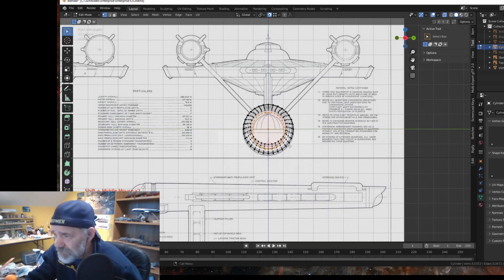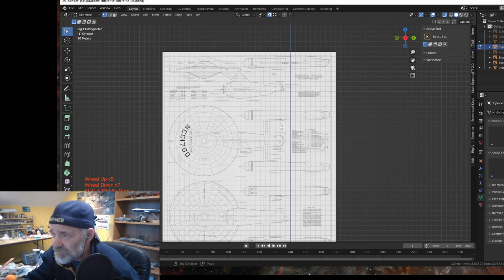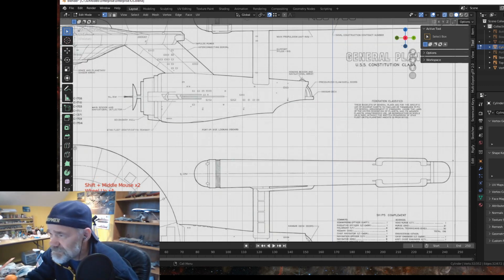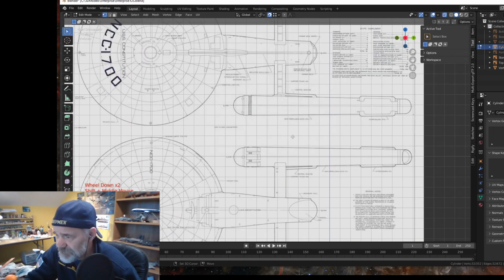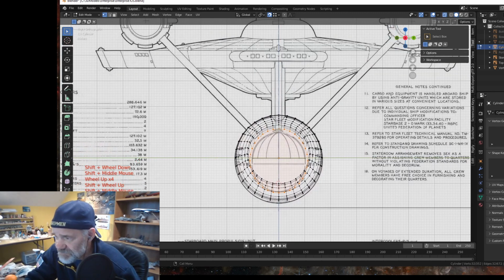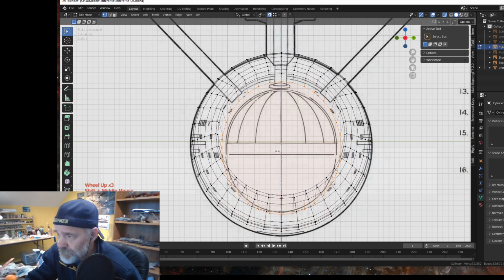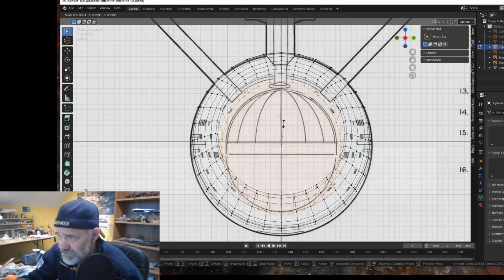Homing beacon. Alright, so on the side view, even though this is not the picture, here's the homing beacon, and this line almost lines up with this side of the homing beacon in the rear, in the stern. Right? And we notice that the line we have selected is actually in back of it. Alright, so what I'm going to do is scale this one more time in this view. I'm just going to hit scale, and I'm going to drop that till it's closer.